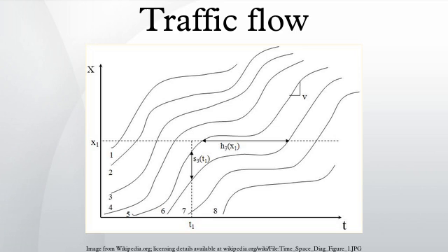The vertical separation between parallel trajectories is the vehicle spacing between a leading and following vehicle. Similarly, the horizontal separation represents the vehicle headway. A time-space diagram is useful for relating headway and spacing to traffic flow and density, respectively.